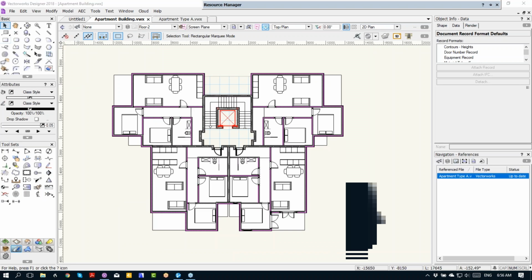Why do I use a separate object to report on a door rather than using the door itself? David, I think I thought I'd gone through that, where if I try to report the door itself, there might be some information that I want that's missing. For example, smoke seals, or the color of the door handle, or the vision panel, or the kick plate, or something along those lines. But also, the problem with the door number is that because I've used the door inside a symbol, I don't end up with individual numbers.